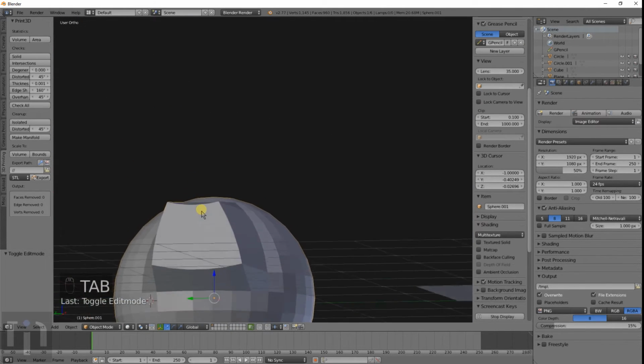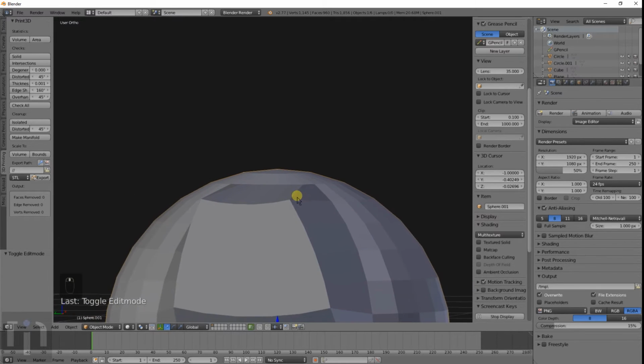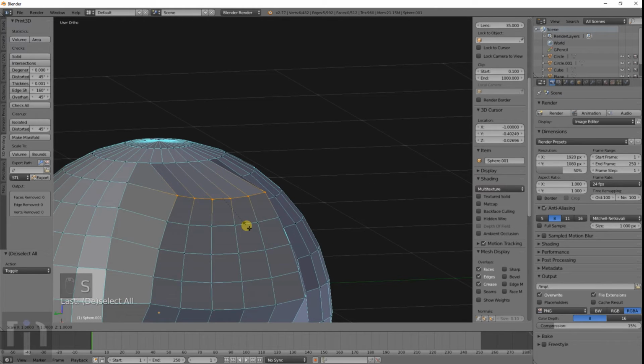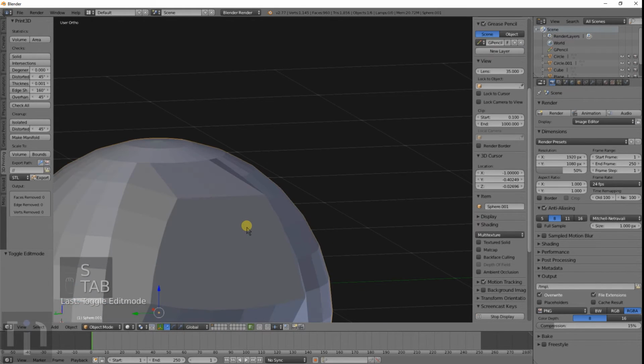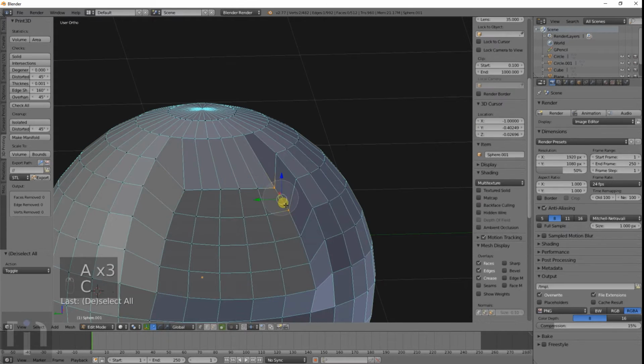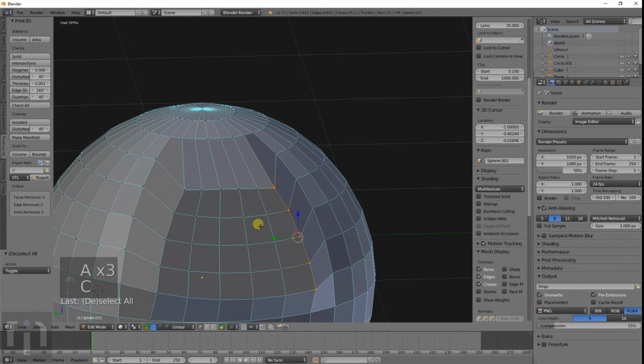And they have a flat spot. If you just need these up here flat, do S or Z 0, makes those flat. That's something that I use quite a bit, is to get things even. Just select all the edge of an object.